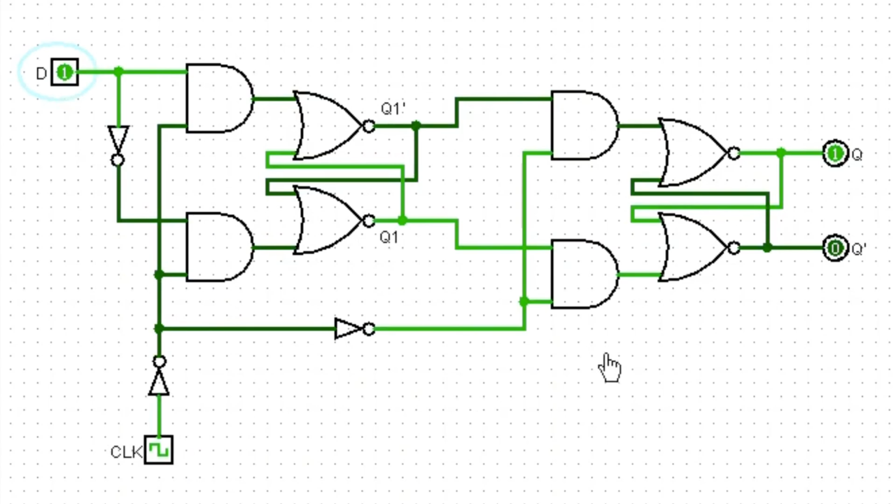In this instance, when the clock is high, any change to D has no impact on the Q output of the flip-flop. Further, if D goes to 0 while the clock is high, the master is not reset until the clock goes to low, and the slave will not be reset until the clock goes from low to high again on the rising edge. This behavior gives us the desired results, a memory device capable of storing either a value of 1 or 0, which changes only on either the rising or falling edge of a clock cycle, thus satisfying the need when creating sequential circuits following a globally synchronous design model.